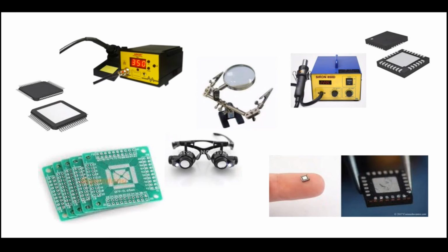You definitely need some lenses. This is a 2x lens, or a 2 to 3x lens, which will magnify the image and can be used during soldering. And this one is for inspection, to inspect the circuit after you solder. This is about 20x magnified.